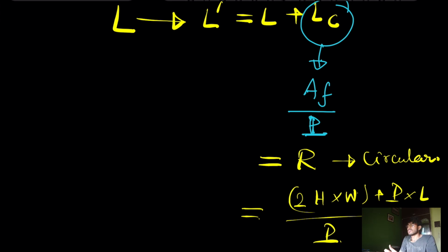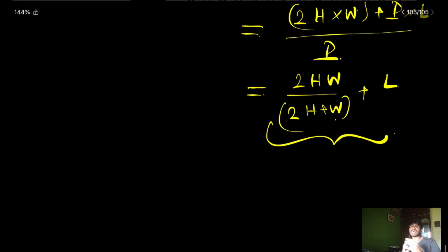So this is an engineering approach to simplify the problem, because the convective boundary condition at the tip is a very complex boundary condition in terms of mathematics. To convert it into a simplified boundary condition, we increase the length of the fin, and we say that the tip has become insulated, almost insulated, that is, the heat transfer is almost zero. Another thing: when can you consider a fin to be long enough?